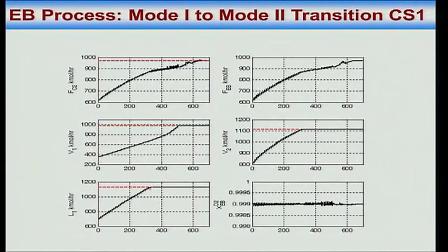So somewhere here L1 becomes active, somewhere here L2 becomes V2 becomes active, and finally V1 becomes active someplace here. In spite of that, I am still able to jack up the throughput by playing with those two unconstrained degrees of freedom, 112 kilomoles an hour to 230 kilomoles an hour, and benzene impurity from 0.04% to 0.09% or 0.09% to 0.04%.